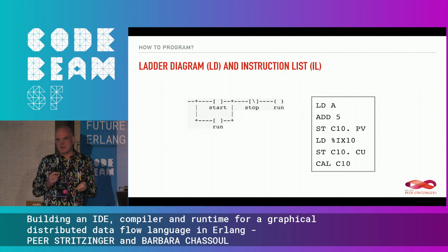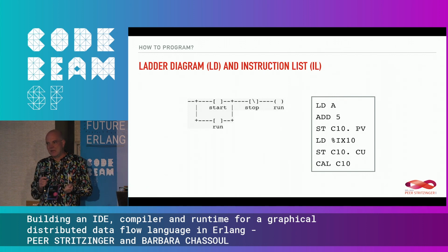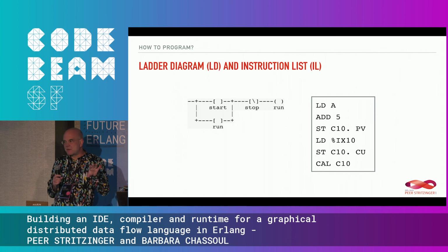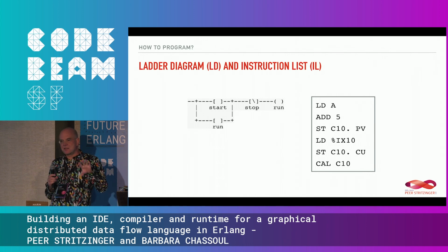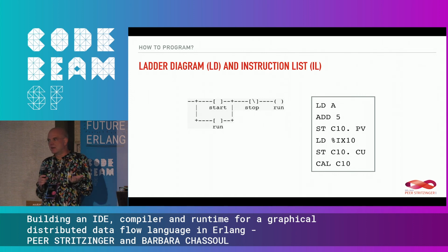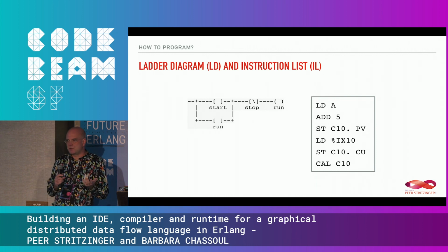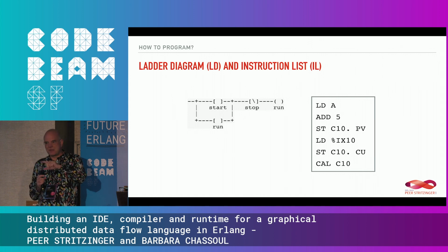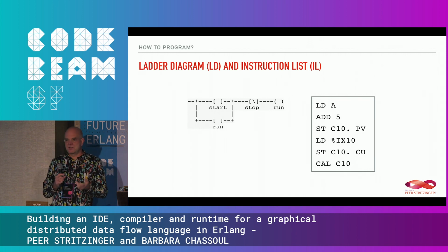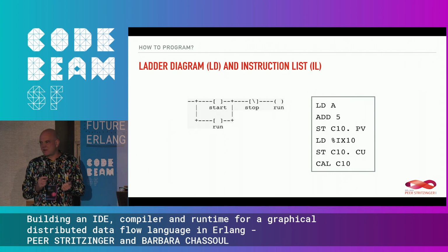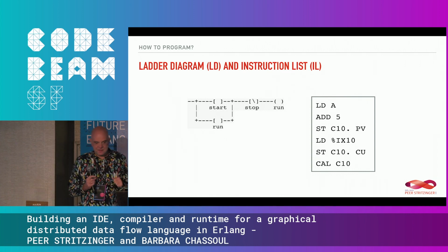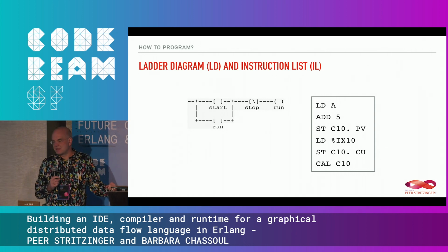Because one thing that the old PLCs all have in common, they run in a loop. Whatever you program, in whatever language you program it, it's translated into one big loop, which constantly runs in a loop. And that's your real-timeness. So twice the loop time is your real-time reaction time, your worst case. So you basically write your program, you measure your loop time, or it actually gets displayed. And when it's too slow for your process, you buy a larger PLC, because then your PLC is too slow. It's a very wasteful way to do things. But that's basically how most of the PLCs still run.